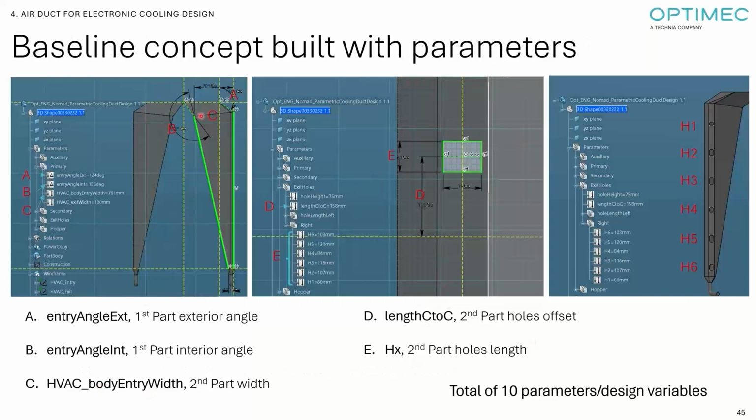So here, a view from the top. If you picture the HVAC here, we would blow the cold air towards two kinds of inverted triangular shapes. And on the side of this triangular shape, we're going to position holes to distribute the cold air towards the 6 racks on each side.